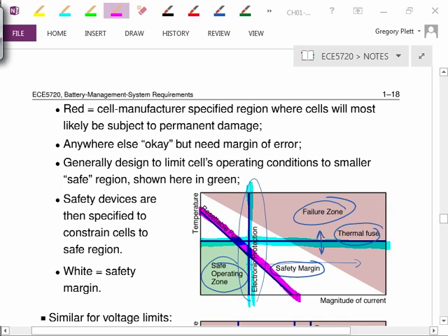We have a third device here, this resettable fuse, which is a different type of fuse technology, which is different from a thermal fuse. It actually opens the circuit when it gets too hot, but when it cools down, it closes the circuit again. It's a slightly different mode. It has a different behavior. So now you can see that for me to get from the green area to the red area, I would have to cross 2 barriers at minimum. So there's a redundancy built in. So even if one of my protection mechanisms fails, there's always at least one more as a backup to prevent this failure. So that's just good design practice.